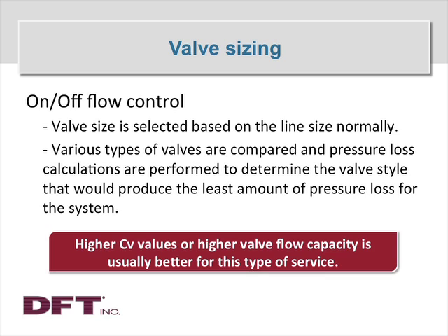And that would probably dictate that the valve should be automated. And if that's the case, if I'm maybe shutting down a section of pipe, do I need to consider block and bleed in that section of pipe? And finally, is automating the valve really necessary, or can I get by with a manual or lever operator?